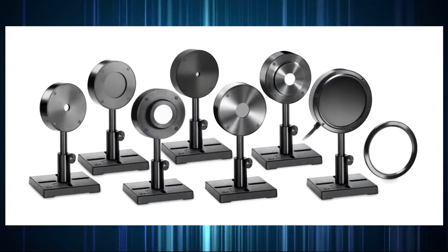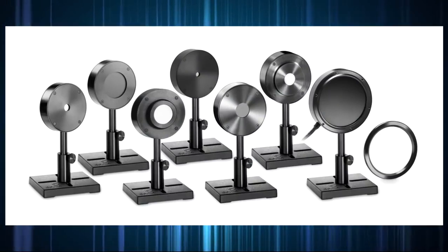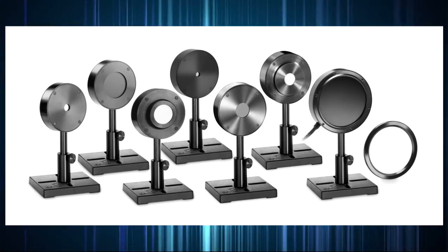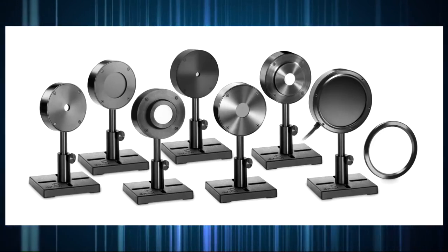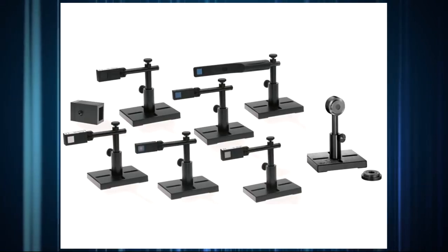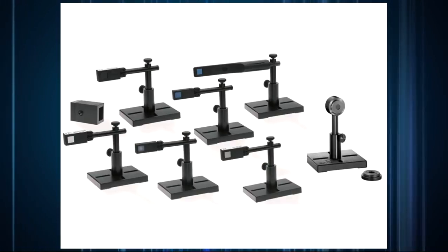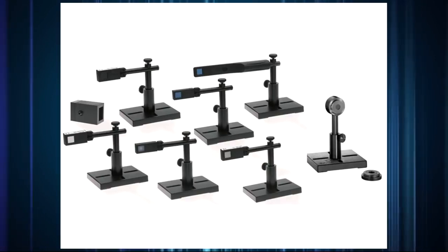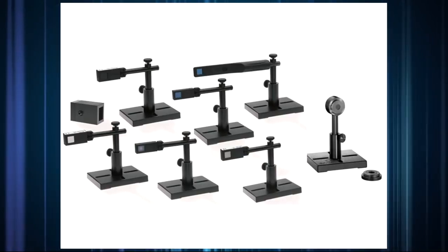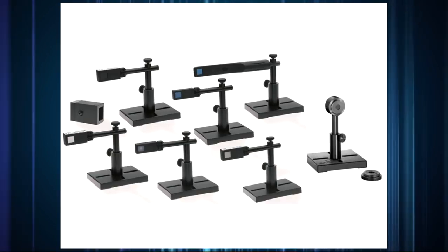For measuring pulse energies, we use energy sensors. These are normally based on pyroelectric detectors, though for the very lowest energies down to picojoules, there are sensors that are based on semiconductor detectors. For measuring very low powers, from picowatts up to several hundred milliwatts, we normally use photodiode sensors. These are based on semiconductor detector elements, where light is converted directly to electrical current, which is then measured. Ophir offers several types for different spectral regions and power levels.